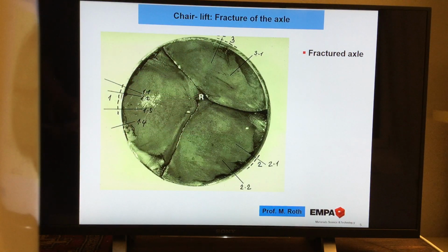Now you think very carefully. Normally, I think we can exclude that a fracture starts here from inside. Why? Because there is a very, very low stress originally on the component. We know already the high stresses are always outside, on the surface of the component.